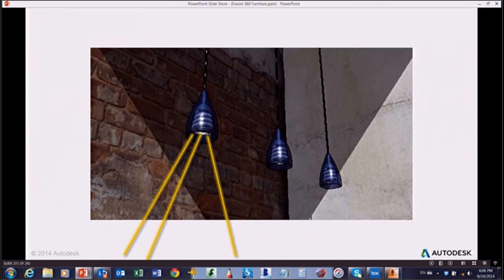If you play with the Revit lighting families, there's a little light source. Students get hung up on those families. The light source is not a light bulb. It's the resultant light. If you want a light bulb, you need to model the light bulb and then give it a self-illuminating material so it glows. Otherwise, you just see the resulting light. You can bring that into the family. And don't cover the light source with geometry, or your project will be dark.